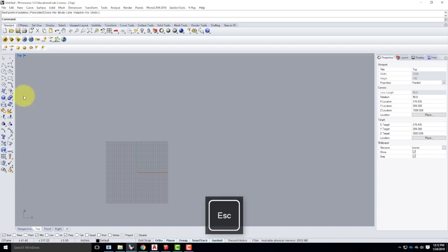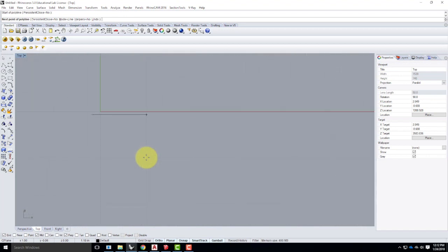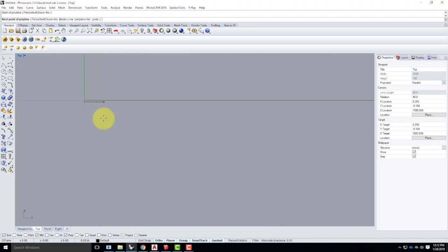The important thing here is even if I thought, I'm really good, I'll just move my mouse right over that point, yeah, I can pick that origin point. As soon as I try to zoom in, you'll see it's not on the origin anymore. I zoom in and say, I could definitely hit that origin this time. Zoom in a little more, and guess what? It's not at the origin. So that's where that coordinate actually matters.